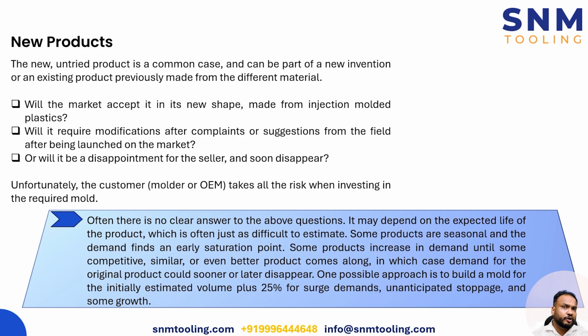A hot runner mold with valve gates, automatic degating, trimming of the gate, and then advanced ejector mechanisms, right? All these things will increase the cost of the mold, and of course the high number of cavities also. But the cost of the product will be less, because for that to happen, we must produce the product in very large quantities from that mold.